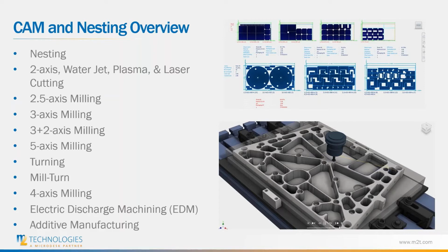Next is the 3-axis milling, which allows for fluid motion through all 3 directions. So working on a flat workpiece like the 2D cutting or 2.5 axis milling, but able to create complex arcs and curves and slopes with the milling operations.